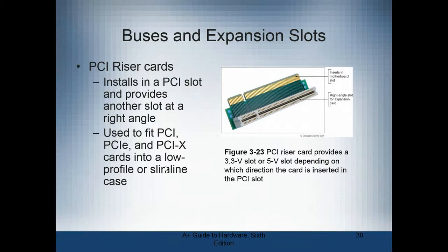This is called a riser card. And we have one machine back here that has one in it. In the good old days, when you had expansion slots, if you had a really flat desktop, the cases might not be tall enough for the expansion cards to go into. So what they did was basically put it in sideways. What you really did with this riser card is you plugged the motherboard into the riser card.